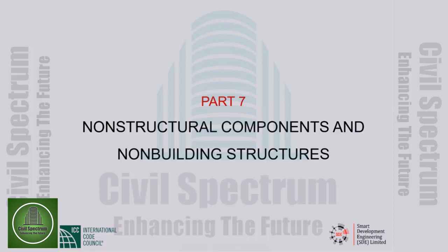Let me look up what table 612 is actually. Oh, table 612, deflection limits. To compute deflection limit except earthquake load, BNBC 2020 table 612 has different construction scenarios. What is the difference between roof members and floor members?